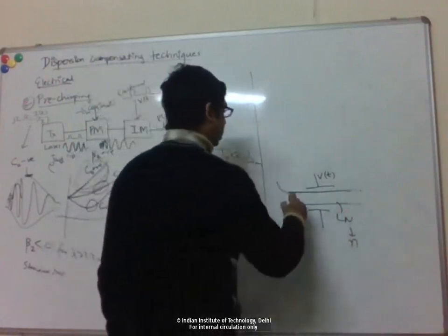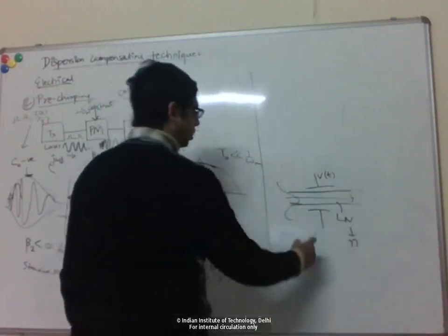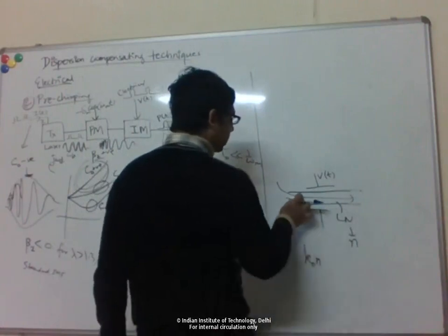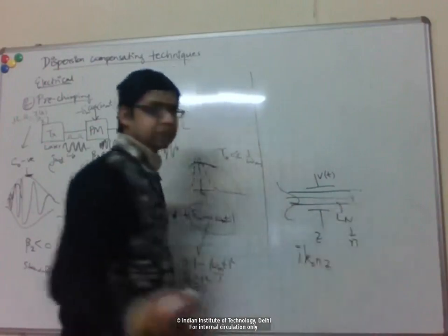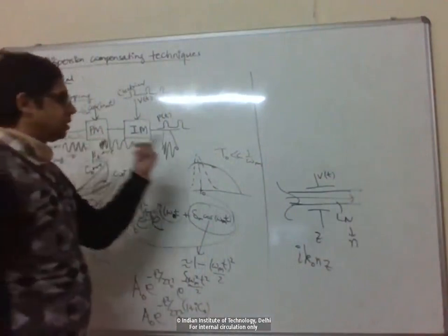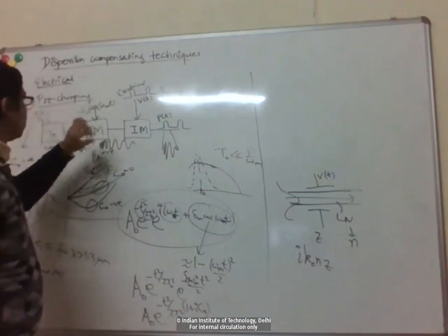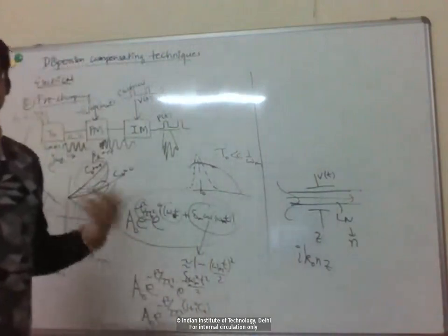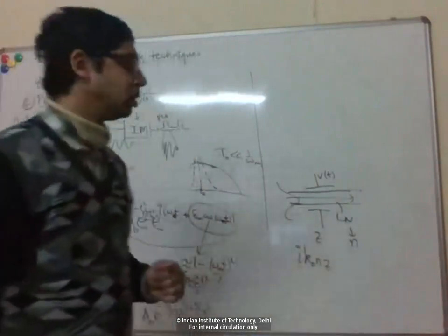Right, so if you have some optical wave passing through, then you know that the propagation constant depends on the refractive index. So if you change the refractive index, then the phase shift acquired through this material will change. So you can straight away see how I can make a phase modulator. I just have some length of this device, lithium niobate, and I apply this voltage, it changes the refractive index, it changes the phase. So the phase modulator is actually the simplest device you can make out of such a material.